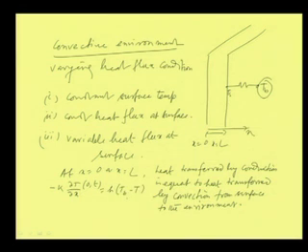This is the condition at x equal to 0, and at x equal to L the condition is minus k into del T by del x at L equals h into (T minus T_b). So there are two boundary conditions for the two surfaces. Apparently it looks like heat is transferred from this surface to this surface, but actually it is transferred in both the surfaces, and this is a cooling environment.